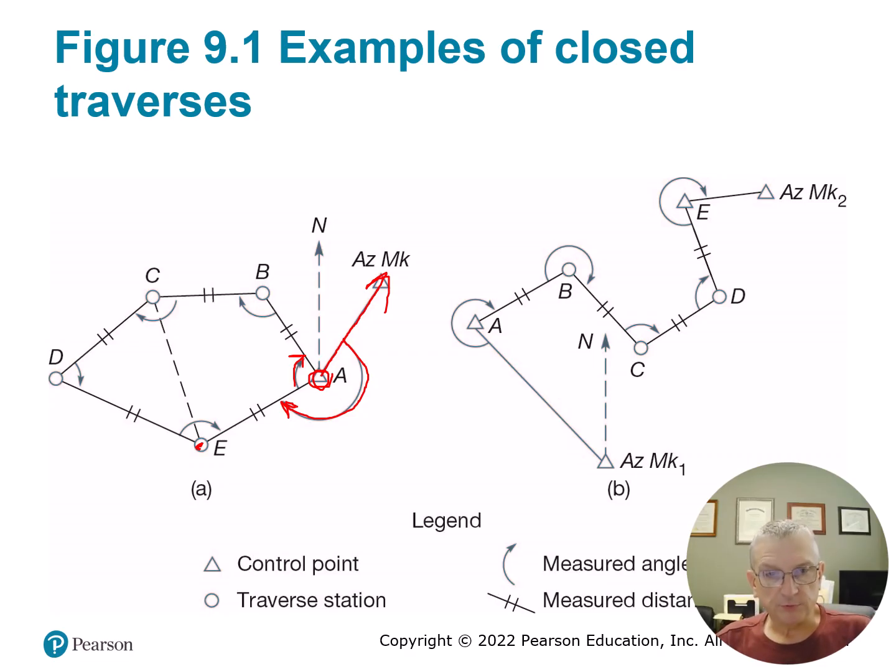Then you would observe the angle and distance out here to B, and then next you would set up on B, backsight A, turn the angle, measure the distance to C, and so forth until all 1, 2, 3, 4, 5 angles have been turned and the lengths of all 5 sides of that shape have been measured. So total stations will measure a horizontal distance. Typically we still measure a slope distance and a zenith angle and convert it to a horizontal distance.